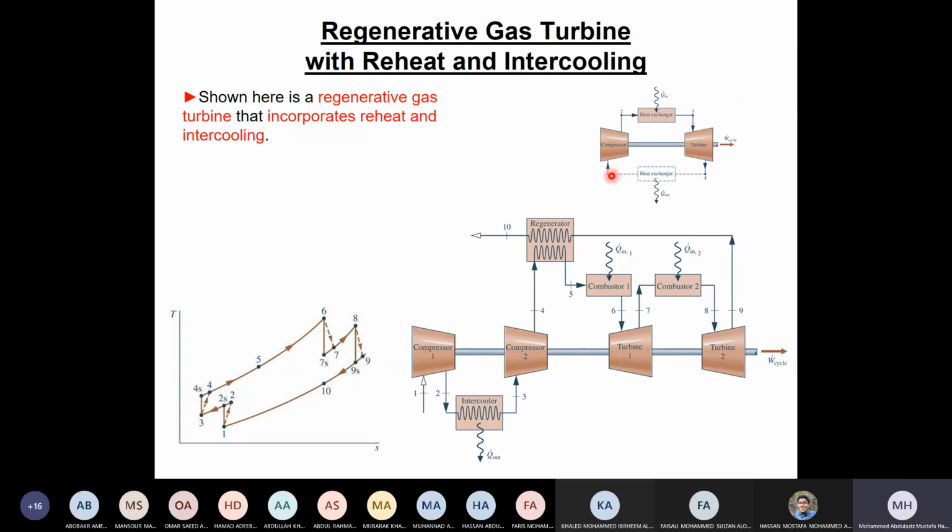Normally we are given P1 and T1 here. Then we are given the compression ratio, so we'll go to state 2. Then state 3 is given, so we can calculate Qn. Then from 3 to 4 is expansion, and we calculate T4 and get the turbine work minus the compressor work. This will be W net, and then divide by Qn. This will give us the efficiency.